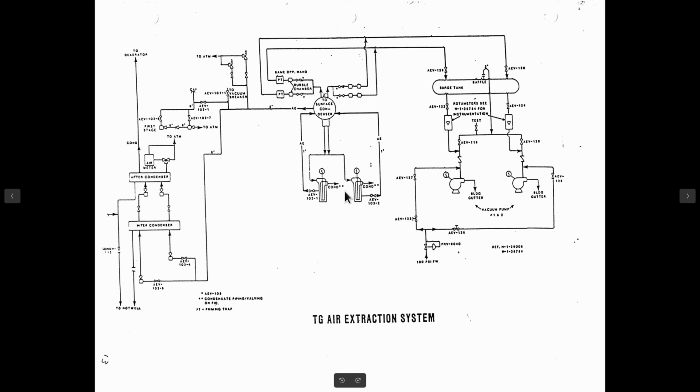This is the air extraction system. This just shows the air extraction on the raw water return on the surface condenser to keep from airlocking it. It took off a little slipstream. Vacuum pumps pulled on the surge tank.